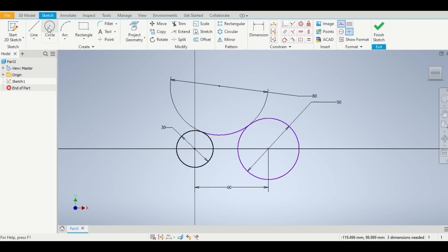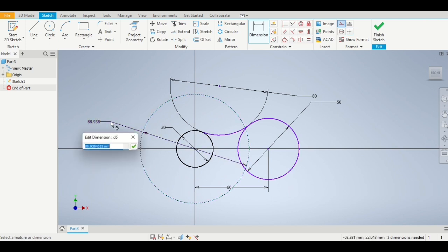So the next part of the drawing is to find the centre point for the R75 arc, which is the internal arc. That's the other arc at the bottom of this object, which will make it look like a kidney bean shape. So how do we do it? Well, we turn on our construction lines, and then we take our R75 arc, and then we subtract our R15 from it to give us a radius of 60, or, as we're drawing a circle, a diameter of 120.